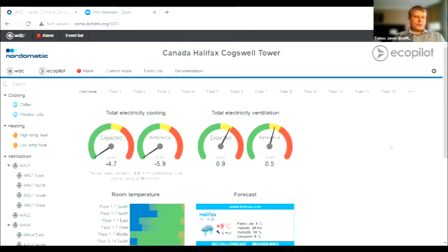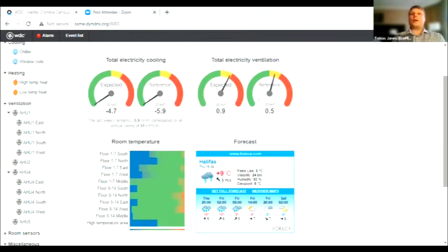Next one is the temperature sensor. So we're saving energy, great, but do we have a comfort issue in the building? The next step is to check what the temperatures are throughout the building. Now, I logged in here today and I see that there are a bunch of cold sensors. I looked at them and they're reading 0, which means they're actually not reading. So I sent out a quick email just before we jumped on here to let them know some of their sensors have stopped reporting. But the ones that are reporting are the important ones.